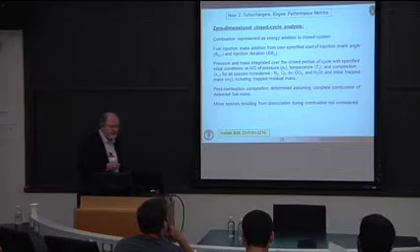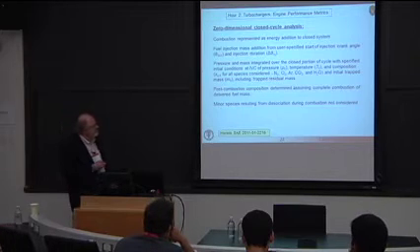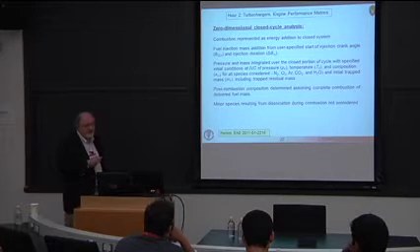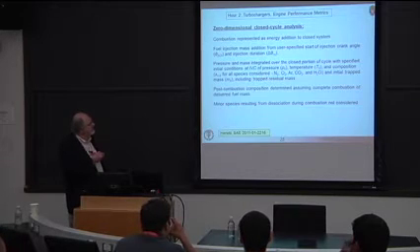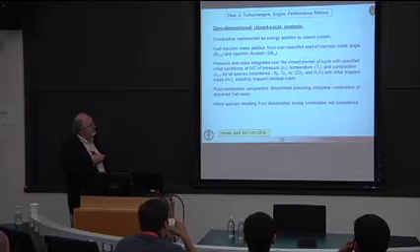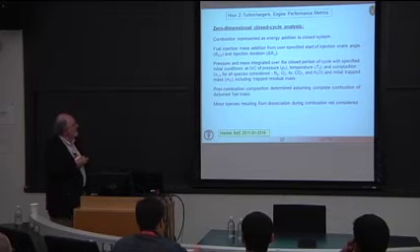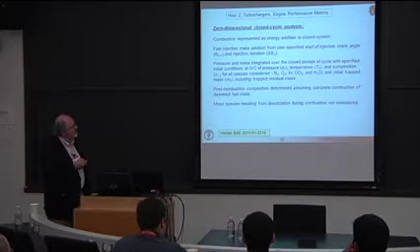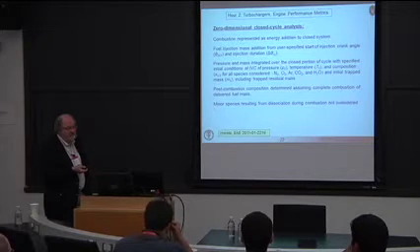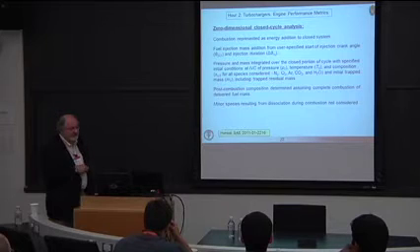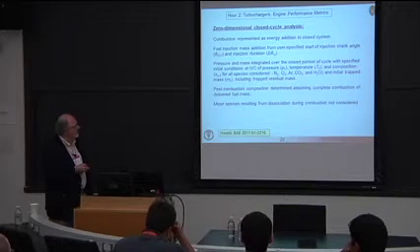So zero-dimensional closed cycle type analysis is very helpful when one designs an engine system. But the first thing here is really the downfall of those models, if you like, and that is that the combustion basically is just represented as an energy addition to the system. And you have to make some assumptions about how that energy is added to the working fluid.